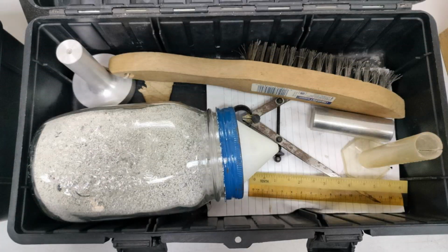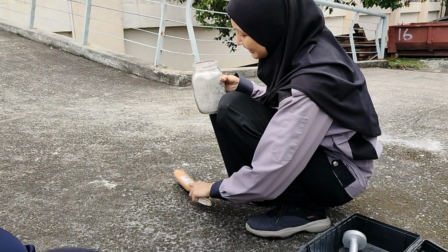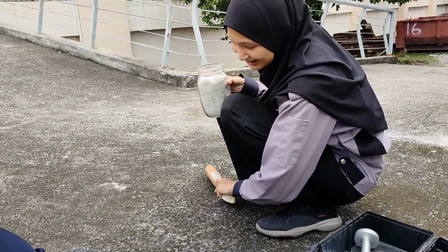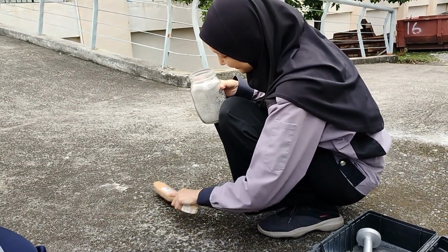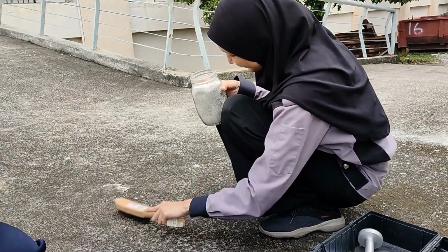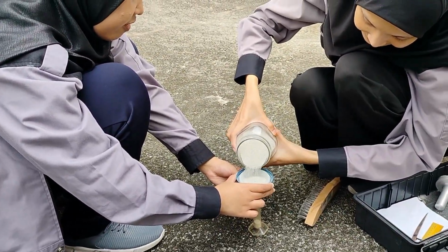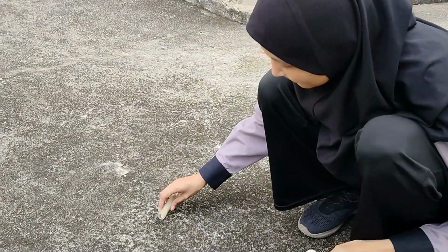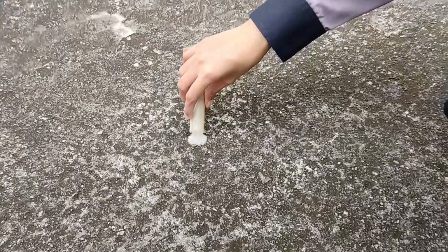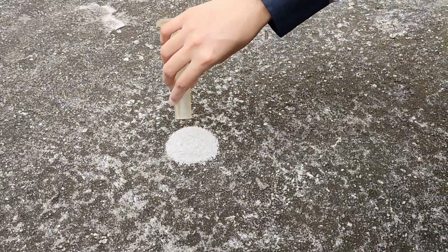Next, we conduct sand patch test. The apparatus of sand patch box consists of brush, steel pad, measuring cylinder, sand passing at 60 micrometer sieve and ruler. First, make sure the pavement surface selected was dried and cleaned it with brush from any debris, dust and fine granular particles. Next, measure 20 milliliters of sand using a measuring cylinder. Then, pour the sand onto the pavement surface where texture depth is to be examined in the form of heap